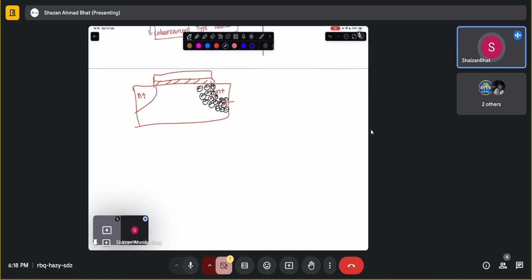That means it's a PN junction, where this is the depletion width, as you have studied in the PN junction. Similarly, on this side, there will be positive ions, and this will be the negative depletion region. It will be spread towards the P-type substrate. So this entirely is basically the depletion region, up to here. This is the huge depletion region.